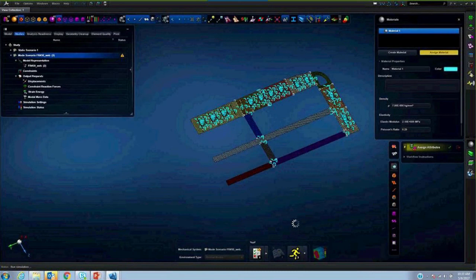So what you saw here, we selected one of the subassemblies in the model. It is not one part. It is many parts constituting that frame. And we created a mid-surface, and we connected those parts with an edge tie connection. And we are running the simulation to see whether this particular subassembly is ready to be assembled with the rest of the model. So it's just about done.